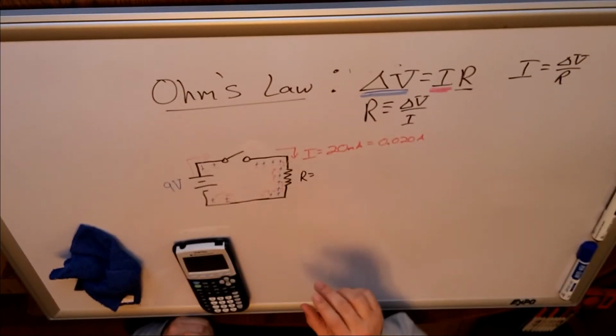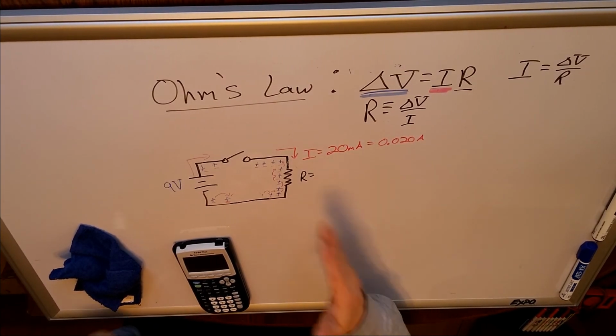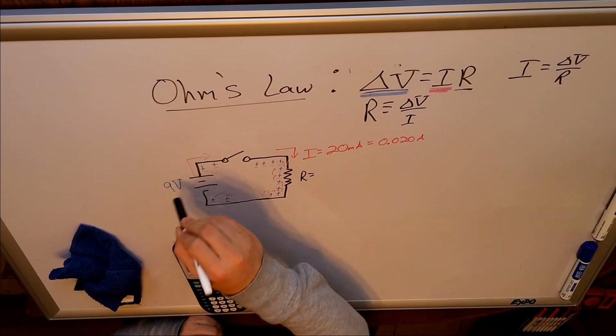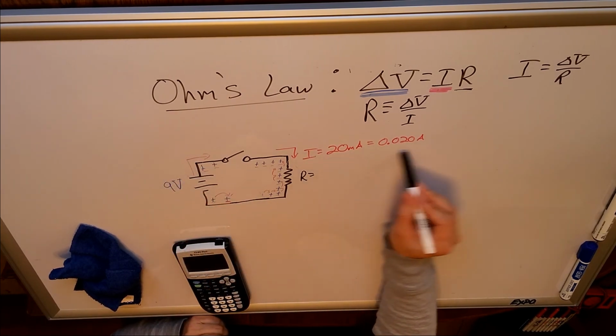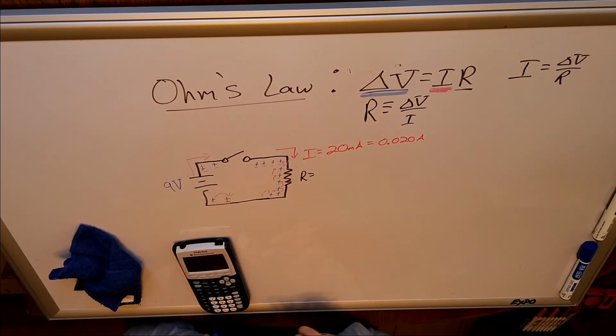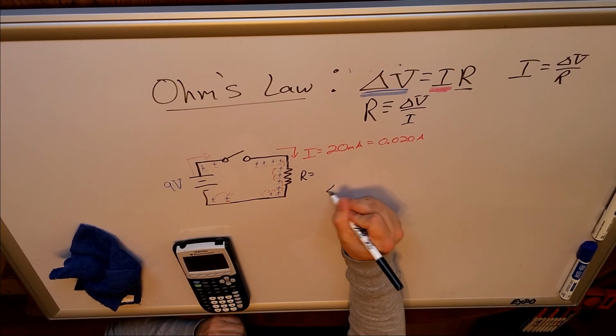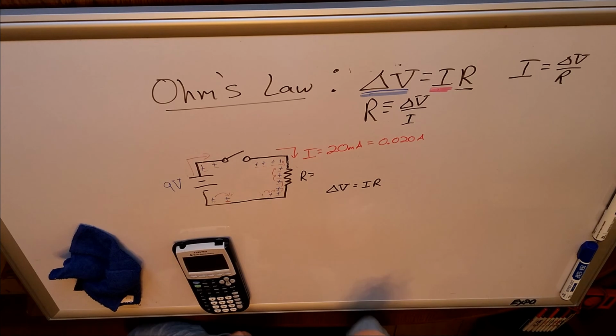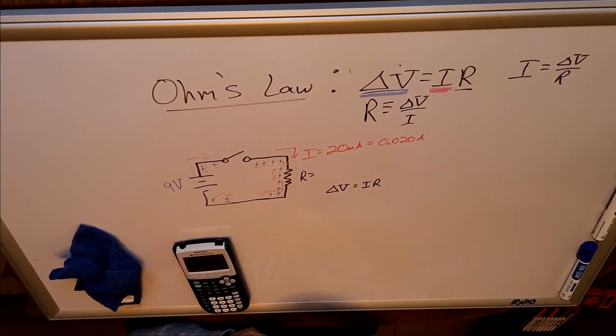As I change the resistor, as you saw earlier, we change the amount of current going through. And if I want a 9-volt battery to power it and no more than 20 milliamps going through that circuit at any point, then I can use Ohm's law to find what I need. V equals IR. Now, this is a bit of a simplification.